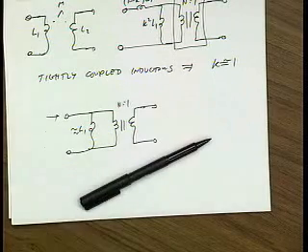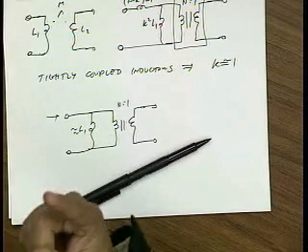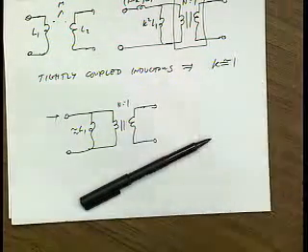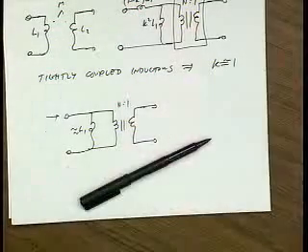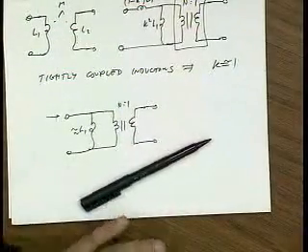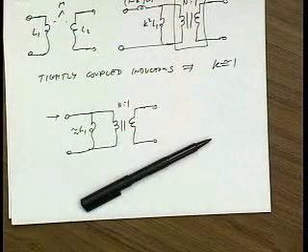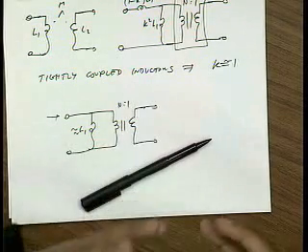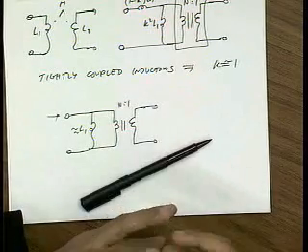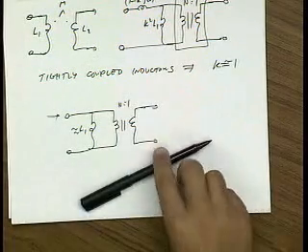The other problem with transformers, of course, is that the voltage is fixed. So if I'm on a 120 line, I have to use a different transformer than a 220 line. So if you traveled with a transformer, you needed to carry around 2 transformers with you. Nowadays, of course, we use switching power supplies, and so we don't have to worry about that. But that explains why the transformers were bulky, they're big, and they had the magnetic core, which made them heavy.